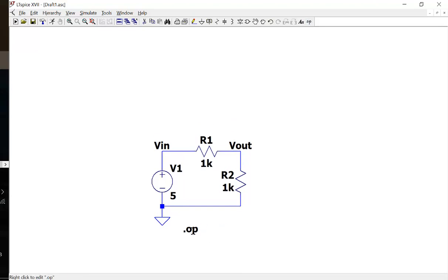That's a SPICE code, I think, or SPICE simulation command. The .op is operating point. It's being used for transistors' operating point, but it's being used here as well, even though we are not running an operating point. For a DC circuit, it's just gonna give you a report showing you all the voltages at each node and all the static currents running through the resistors. And you won't see any waveforms by running .op simulation. Okay, I just put a .op here and run.